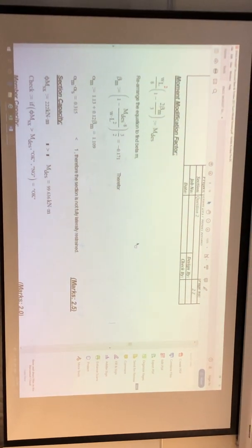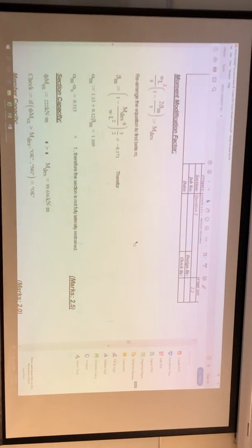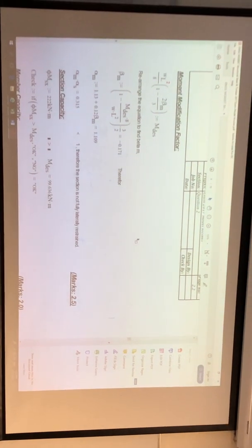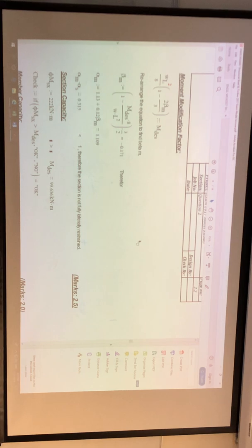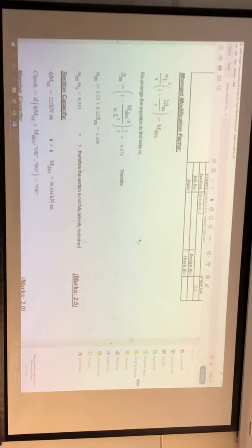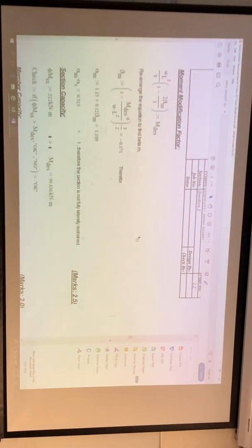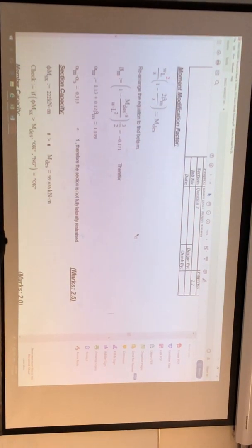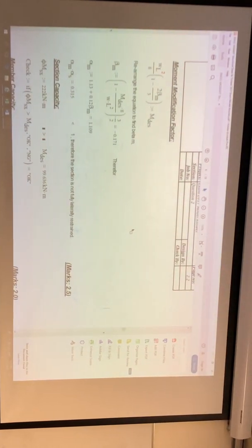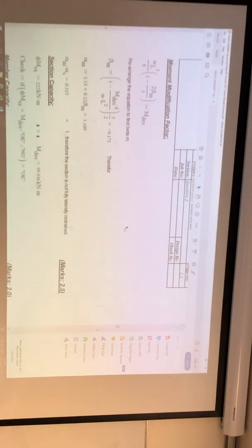While in the assignment, you had the tools, you had Multiframe to find out exactly where to. If you couldn't do it, just split the beam into 4 segments. Like that you can in Multiframe. You can divide, right? Okay, your segment is at 1/4. You divide it there, and then that segment there, divide that into 4 again. So then it will give you the numbers at those 4 points. You know what I mean?